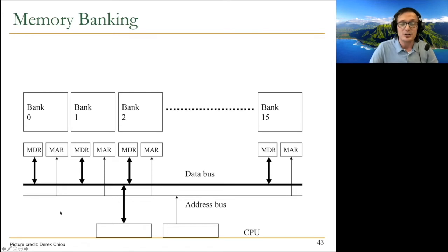And basically, you can write to one memory address register in one cycle. So if you interleave the words consecutively so that you can actually access consecutive words in consecutive cycles from different banks. So if your memory takes 10 cycles, for example, by having 16 banks, you can sustain one element per cycle throughput from your memory every cycle, assuming the consecutive words are in consecutive banks. Right? That's the good part. So your word 0 is in bank 0, word 1 is in bank 1, word 2 is in bank 2, ... word 15 is in bank 15.